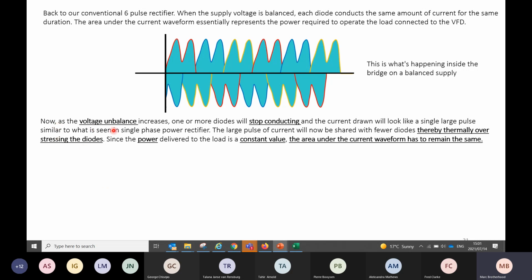So let's have a look here. Now, as the voltage unbalance or imbalance increases, now we're not at 400 volts. Two phases might suddenly be running at 400 volts. Now suddenly I have too many single phase loads switching on, like microwaves, ovens running, people switching kettles on in the office, in the factory. And now suddenly the pushing pressure, let's say on my red phase, drops from 480 volts down to maybe 380 volts. This is pretty much what I'm trying to tell you.